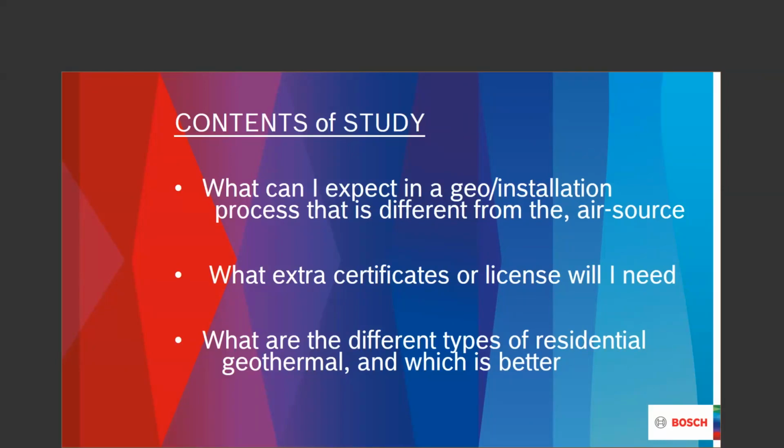The only thing I worry about on a geothermal system is the incoming water temperature. If I can design that energy plant for a certain temperature, a certain amount of BTUs inside that temperature, then I can truly design it for the maximum BTUs at the lowest outside air temperature.